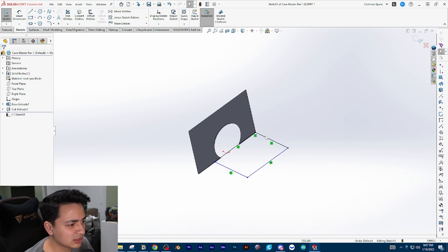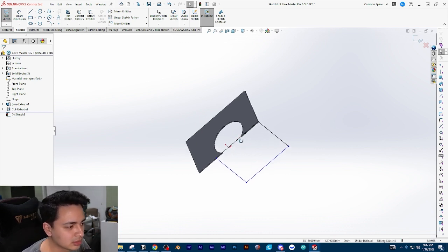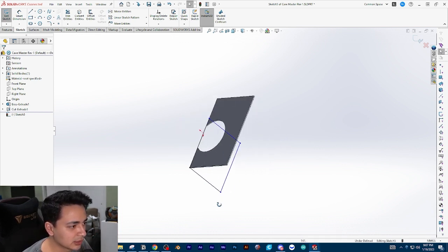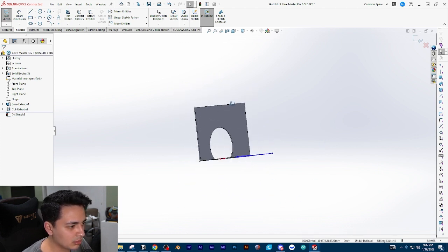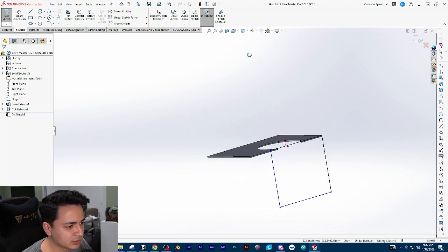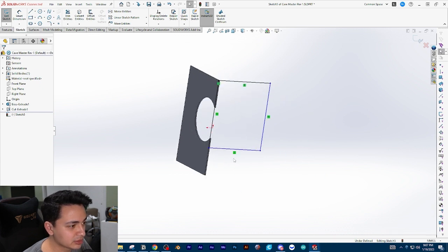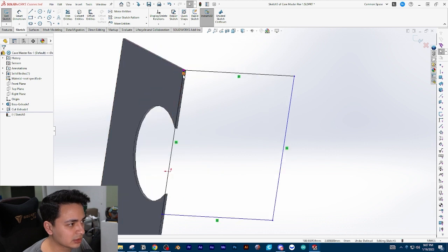So basically we want this rectangle to be aligned to the floor at a 90-degree angle, and it's just going to be another like cardboard sheet, right? So we want these to like perfectly align, right? So this is a good area where I can show you the constraints. So right now it auto constrained the corner because we picked the corner of this rectangle to start our corner of our new rectangle. This is constrained by coincident.